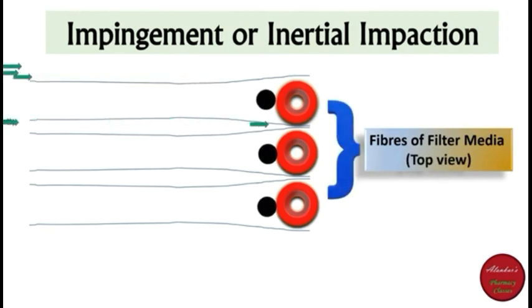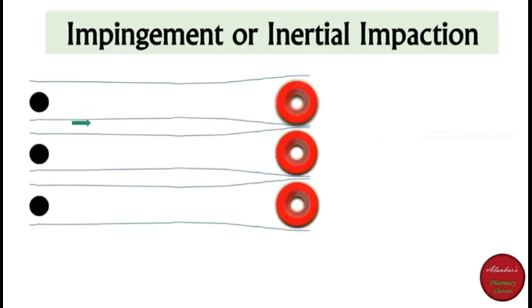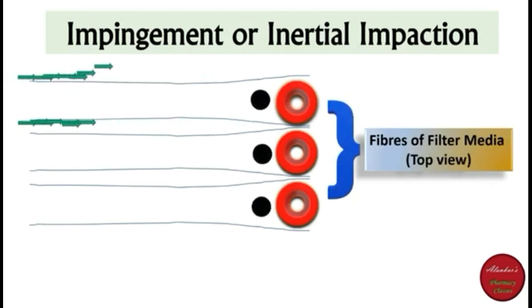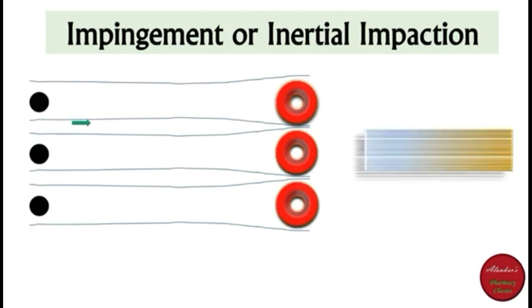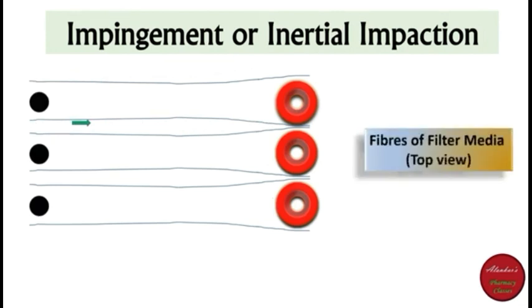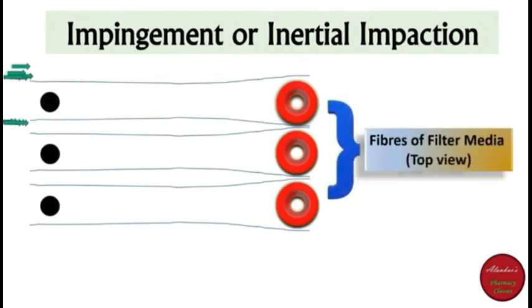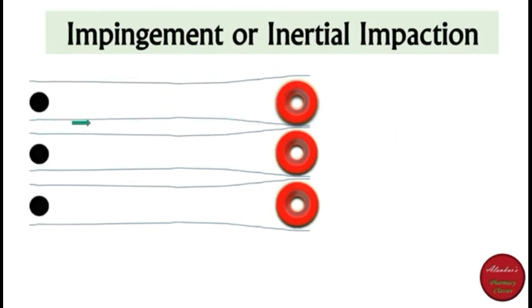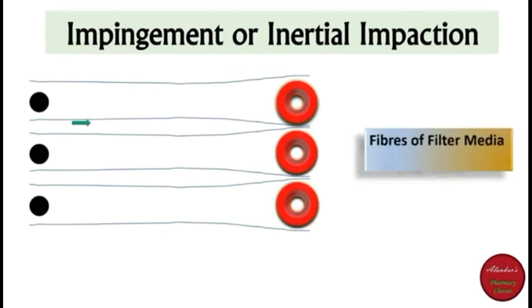And the second equipment is the vacuum filter, and in the vacuum filter the filter leaf is used, and the principle of the filter leaf is surface filtration, and the characteristics and use of the filter leaf is that it is used for slurries containing 5% solids. And the next equipment is sieve filters.